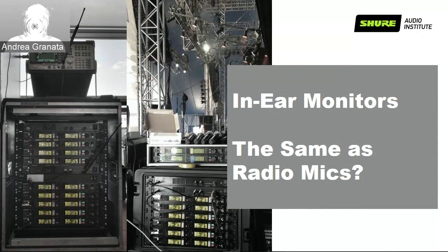These can be completely unrelated. One can be a voice, and the second one can be background music or a program or whatever you can imagine. Two unrelated signals go in the same transmitter to the same receiver, and then at the receiver stage, you may decide how much of signal A and how much of signal B you want in your earphone.